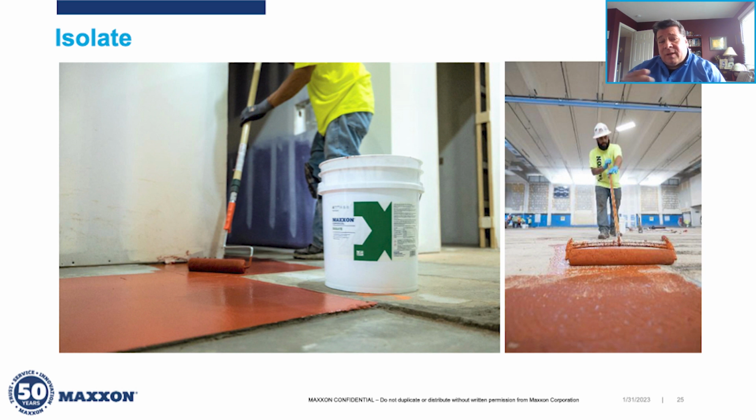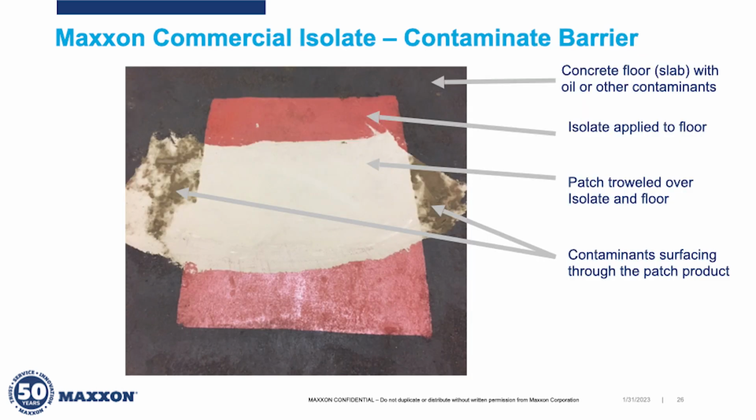So if it does seep into a crevice or a hole in the slab, you want to brush that away so it doesn't puddle. And you want to make sure that you're holding this material to a 600 square foot per unit coverage. So it may take putting some sort of grid pattern across the slab with your chalk lines so that you know that one unit covers 600 square feet, because over the surface it will cover like a paint, so it will go further if you allow it to, but this needs to be put down at the correct mill thickness. So you want to grid off your sections and hold each unit to a 600 square foot coverage.